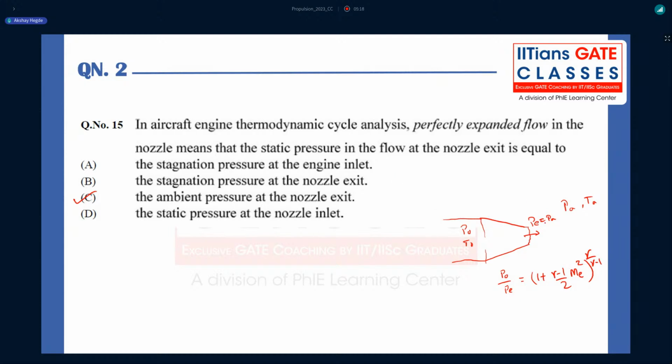One part is that the nozzle is going to expand the fluid to the exit pressure condition, not to the exit temperature condition. Though TA might be the temperature of the surrounding fluid, the exit plane temperature need not be equal to the ambient temperature.